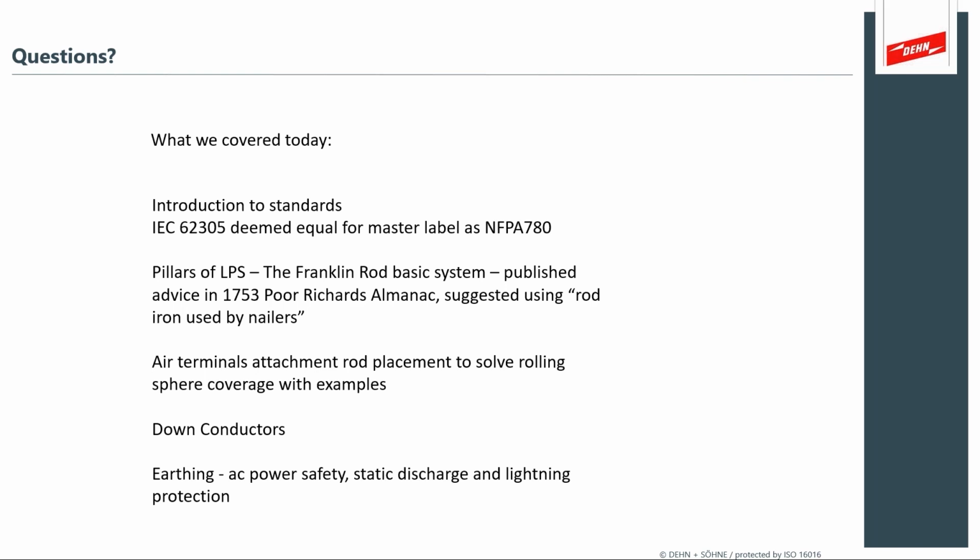And while we're on this topic, I brought this topic up because we have a question here. Is it preferred to have these down conductors inside of the concrete with the reinforcing and the rebars, or to be on the outside of the building with down conductor holders? If you're going to use your natural structure, then the standard indicates that the down conductor should be buried within that concrete pillar. That's what we've seen. You can derive that from the standard. If you're not going to use the pillar, then you can have your down conductor mounted as the structure allows.